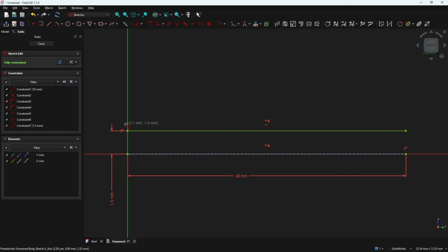So let's create this. Select polyline, select this point here, make a line here and another one here. It is orange because we have two constraints here. This line is vertical and coincident to this point, so it is the same thing. Just delete the coincident here. And now go to sketch dimension.